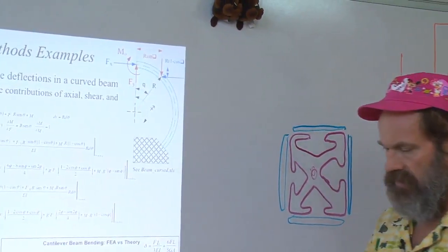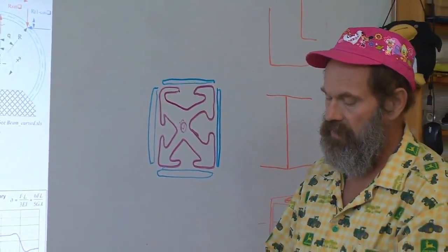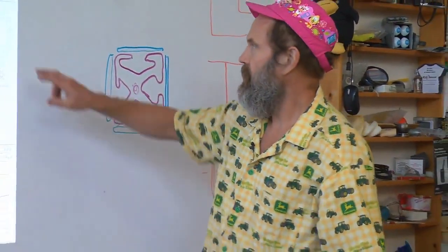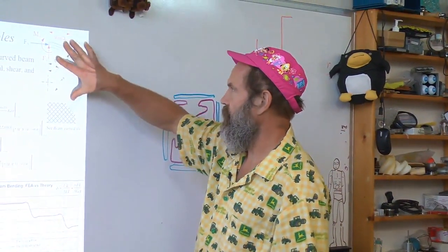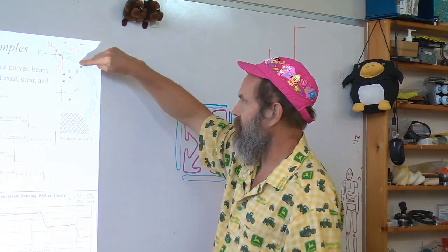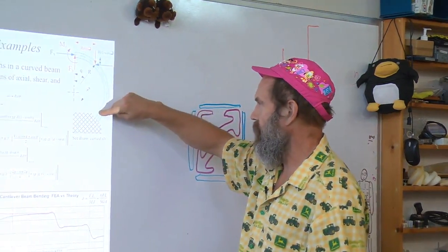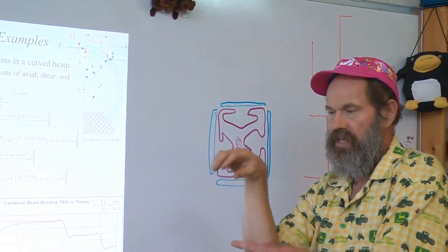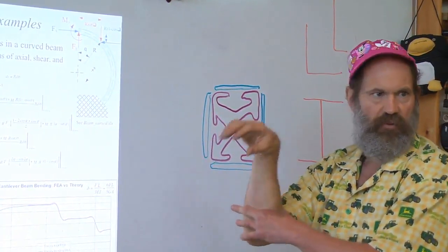You'll have it in the context of, for a curved beam with this arc, how it deforms, the stress and deflections as a function of the loads, which would allow you to play the what-if analysis of how big of an arc I need, for example, in order to get the stiffness of a spring.